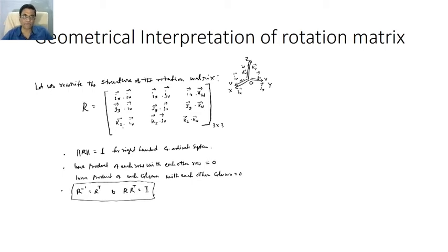And the columns are representing the inverse one. So with the inertial coordinate frame, the projection of the unit vector of the inertial coordinate frame with the x-axis of the body coordinate frame, the projection of the inertial coordinate frame with respect to the y-axis of the body coordinate frame, and the projection of the inertial coordinate frame with respect to the z-axis of the body coordinate frame. So that's important to know, and since it has tremendous application, we should know about this geometrical interpretation.